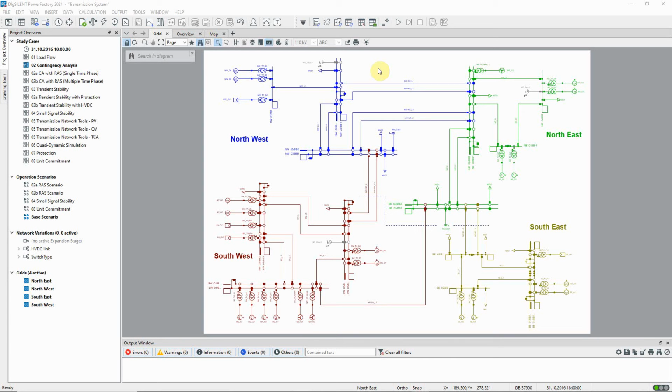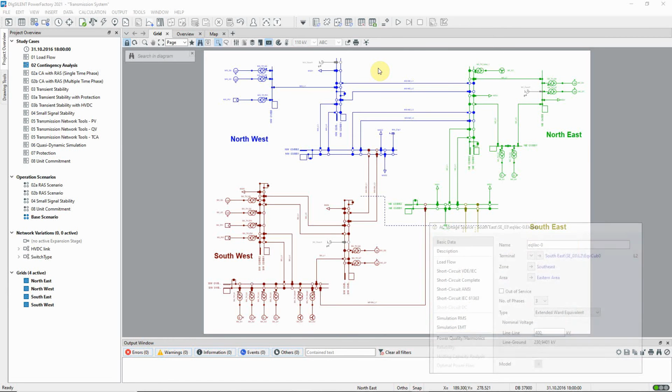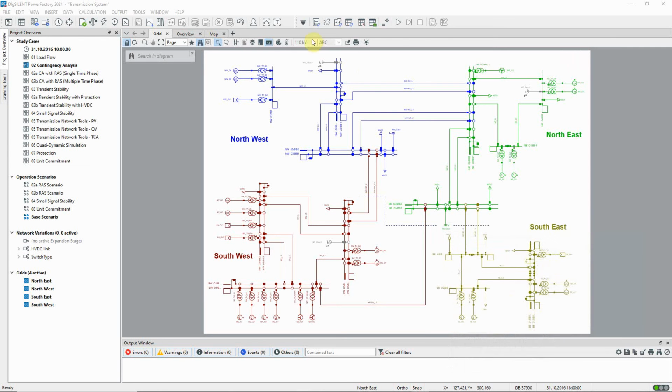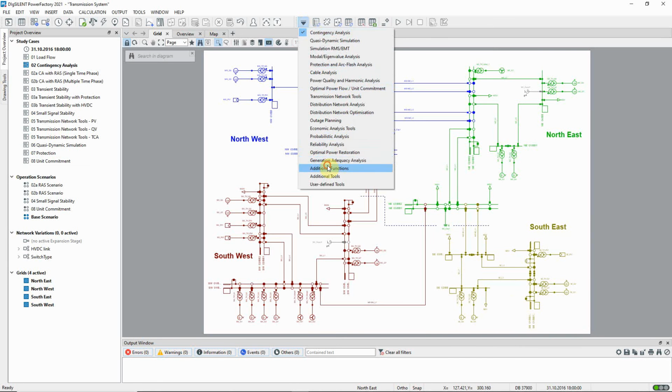When dealing with a large network model, it can often be the case that some parts of the network are of little interest for the purposes of a particular analysis, or are of a confidential nature. Network reduction offers the means to remove these parts of the network and replace them with equivalent impedances and voltage sources. Reducing the network in this way also has the benefit of speeding up calculations, whilst preserving the integrity of the solution. The network reduction command is found in the additional functions toolbox.